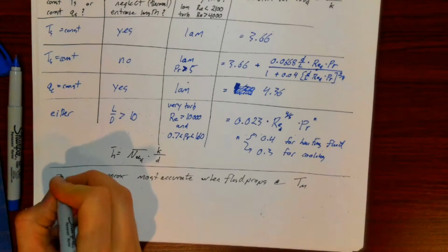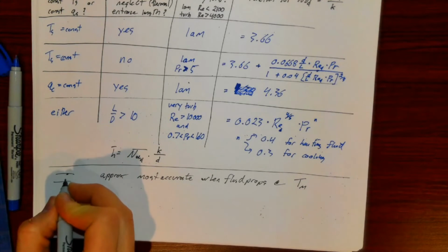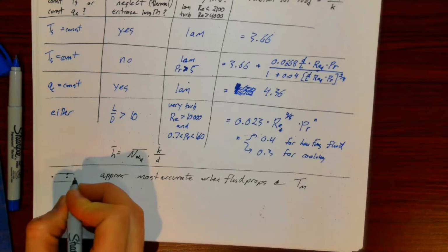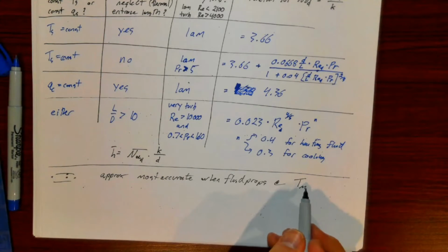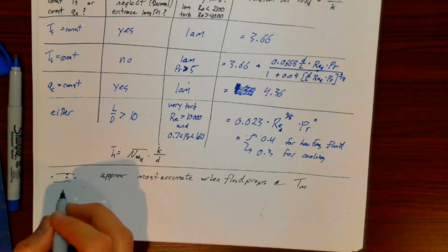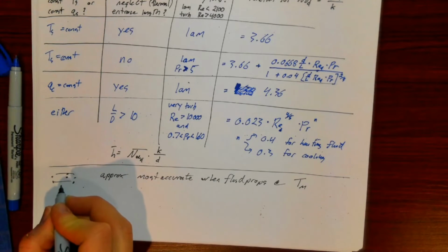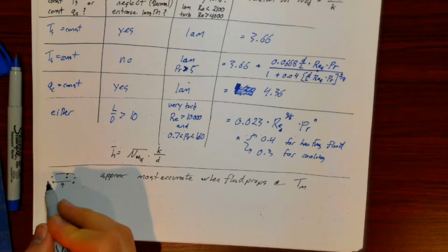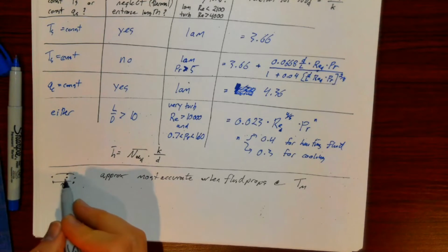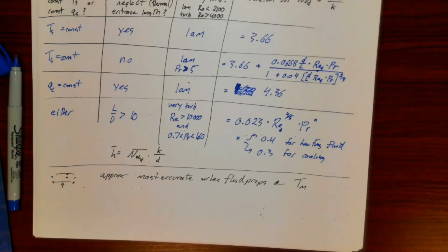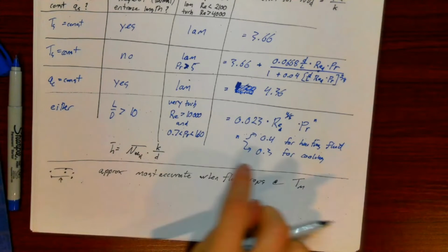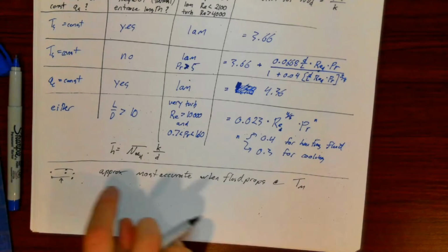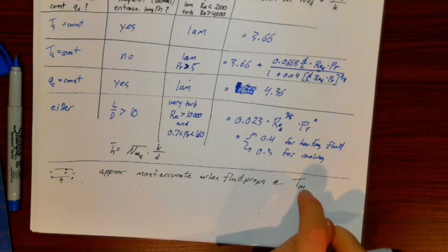So strictly speaking, we know that maybe the fluid close to the edge is different from the fluid at the center, is different from the fluid upstream and downstream. So if you basically said, hey, I'm going to use the mean mixed temperature somewhere in between my inlet and my outlet, if you can sort of use averages of averages in terms of what your expected temperatures are, then you can evaluate fluid properties at that sort of average temperature.